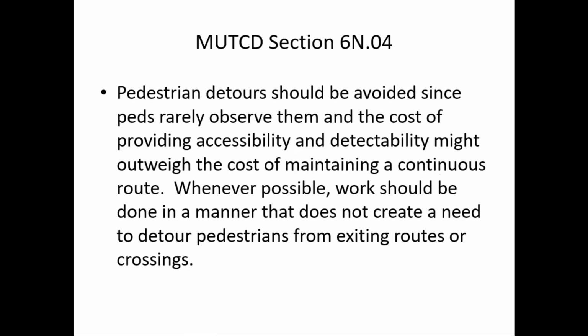I think I mentioned this section in the MUTCD in part 1 earlier today, that pedestrian detours should be avoided since pedestrians, able-bodied pedestrians, may not observe them, and the cost of providing that accessibility and detectability may outweigh the cost of maintaining a continuous route on the original sidewalk. And where we can, the work should be done in a manner that does not create a need to detour pedestrians. So that should be what we strive for.